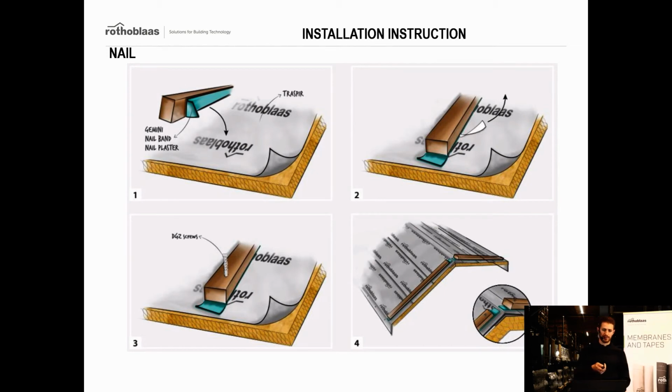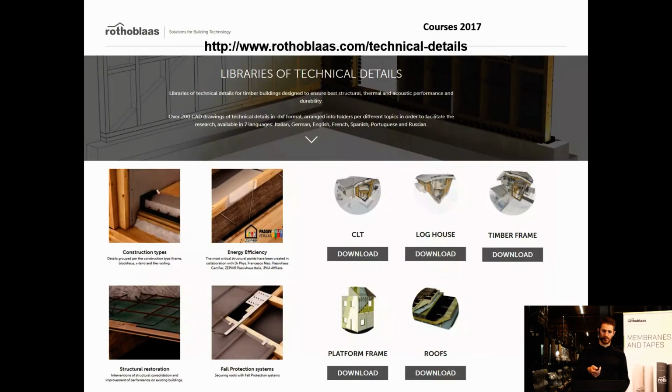This is a very good product because it gives protection to the membrane. It is especially for nails and screws, and when the screw, for instance, is passing through, the product is sealing every single gap, and so you're sure that you don't have air passing through. And that's again something that I would like to show you.